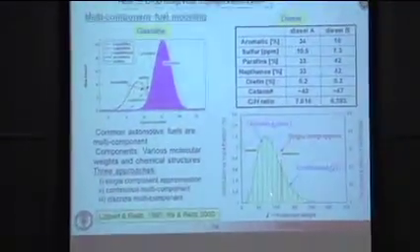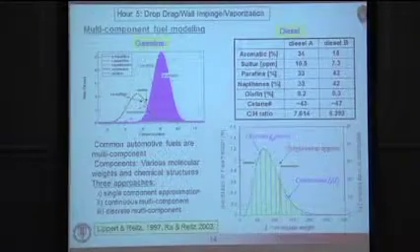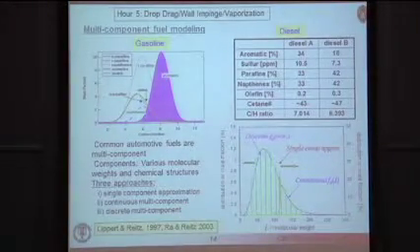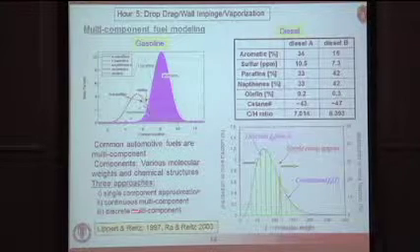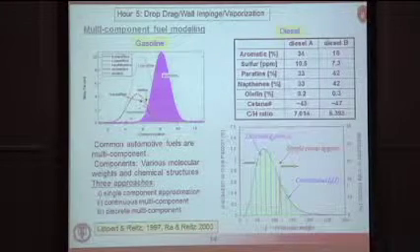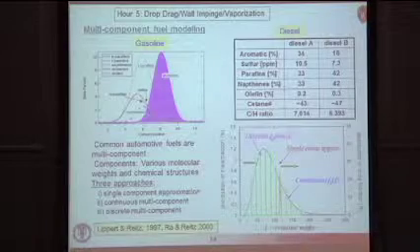The simplest, traditional approach is just to represent the fuel with just one component. Let's call it tetradecane, and we'll say that that represents diesel. Of course, that's not a very accurate way of representing these real fuel effects. So those are 3 different types of models. The one that we're using mostly these days is the discrete multi-component model.